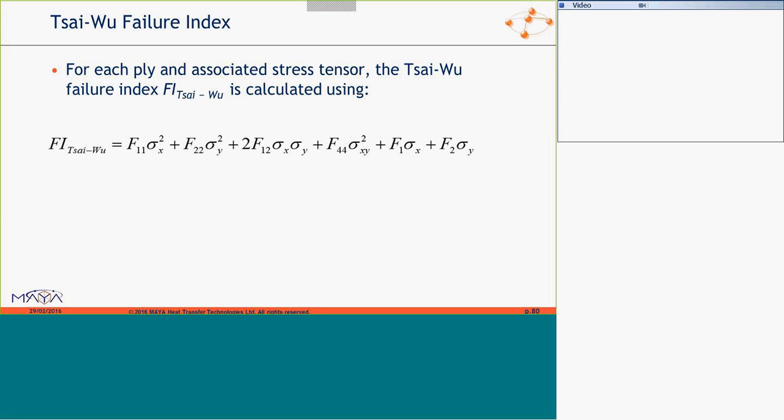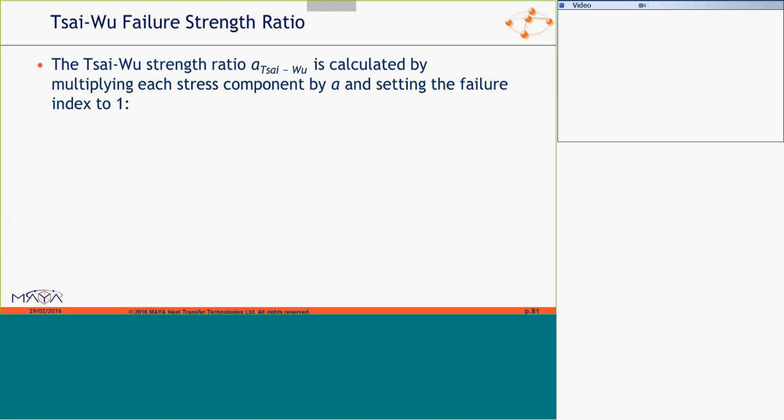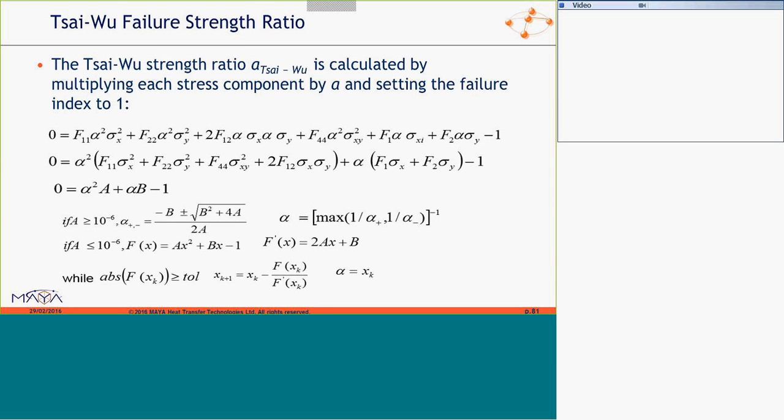It's complicated because if you look at the failure index equation for the composite, you've got some quadratic terms, you've got some order 2, some order 1 terms as well, in terms of the stress tensor. And then the stress is even more involved because you've got to solve for the roots of the second order equation by substituting the stress component. So I'm trying to solve for that.